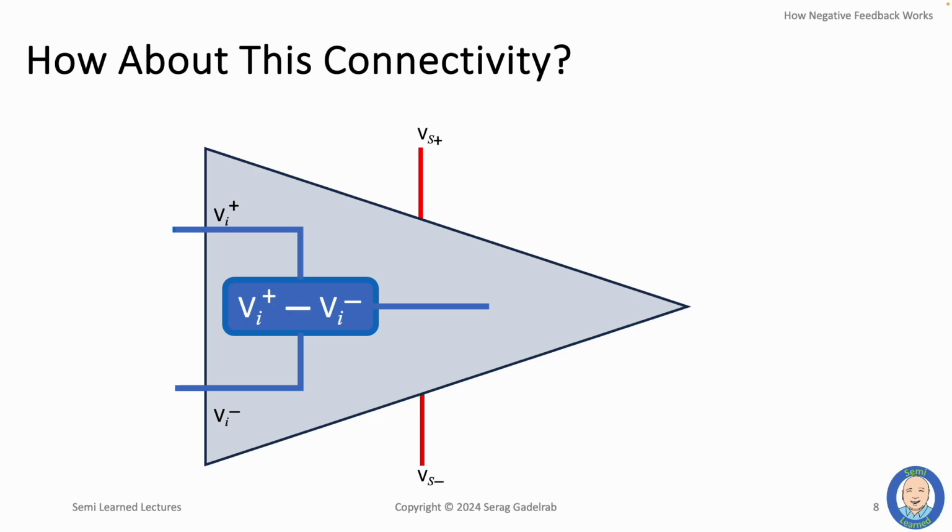What if we connected the faint input signal to the positive input terminal of the op-amp and simultaneously tie the negative input terminal to ground, which always has a voltage of 0? With the ground always being at 0 volts, the faint input signal will not be modified by the subtraction and will show up unaltered at the output of the subtractor. The resulting signal, which is identical to our input faint signal, is ready to be amplified.